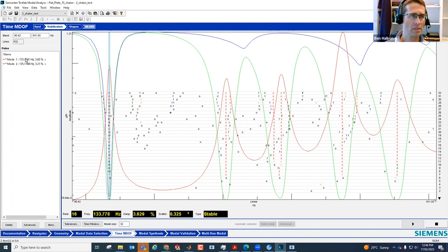I've chosen these 2. You can see we have one mode suggested at 133.75 Hertz, another one at 135.1. Those are pretty close together, even with 1 Hertz resolution, which sounds quite fine. That's only one spectral line apart. And of course, when there's some damping, it's not a perfect peak at that particular frequency. There's clearly some overlap, which is what we see in the sum FRF. We get an estimate of the damping here, 3.6 and 3.2% for those 2 frequencies.